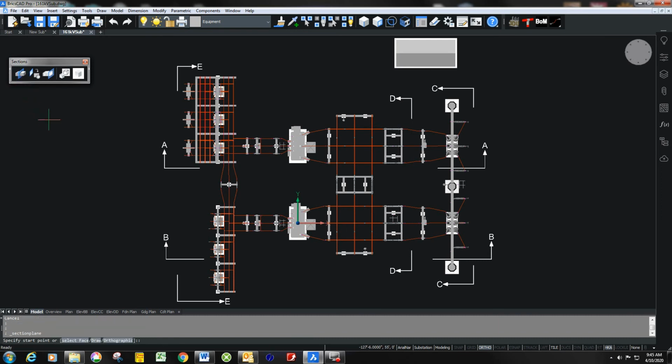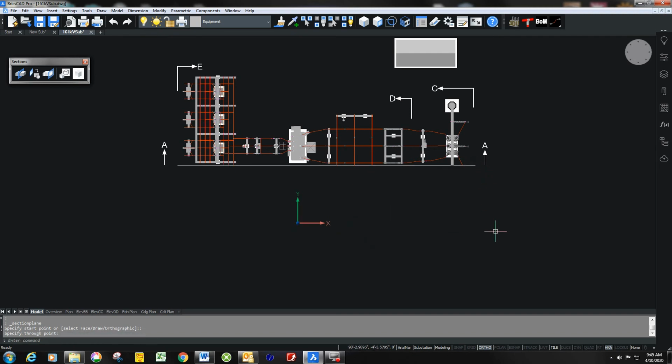So let's just pick this. We go down here. You want to make sure you're down far enough that you're not going to overlap into these structures, and you want to be far enough this way that you cover the entire structure. So we'll start here. Unfortunately, the ortho doesn't work on this, so we just have to eyeball something here that's straight out, and we click, and as soon as we do, we notice that half our substation disappears. Well, let me turn the RT on down here.